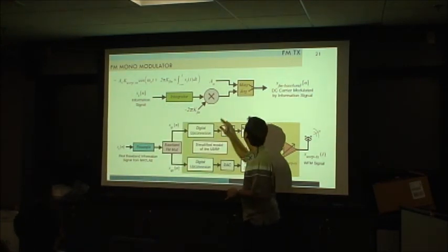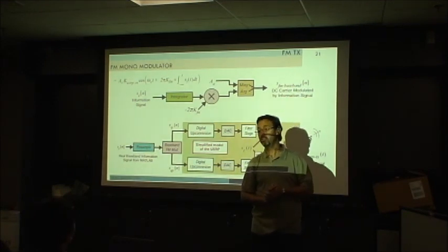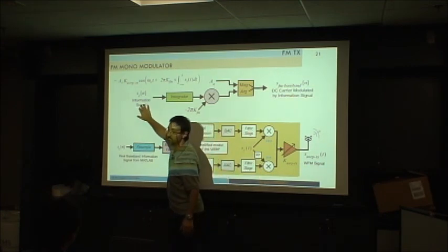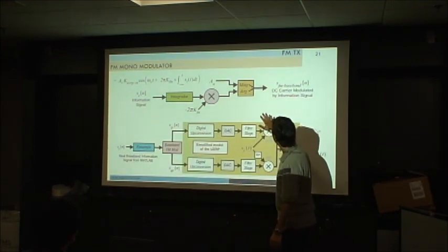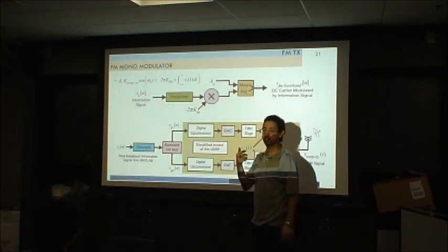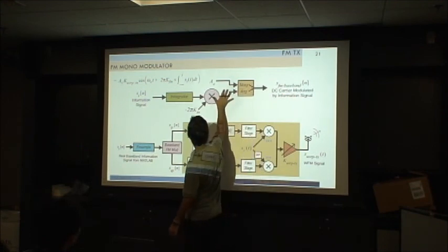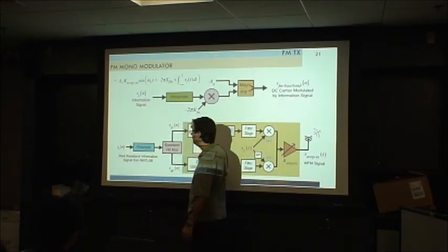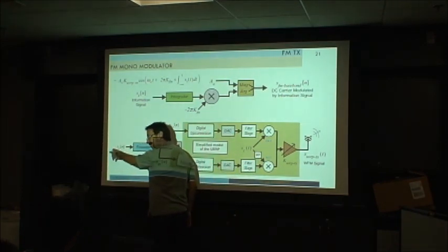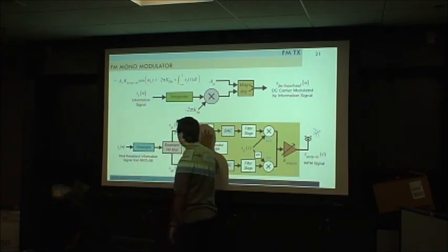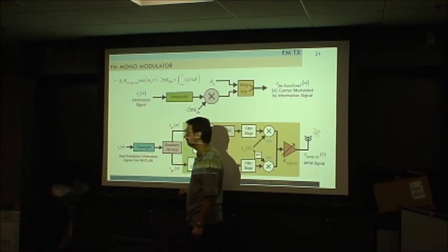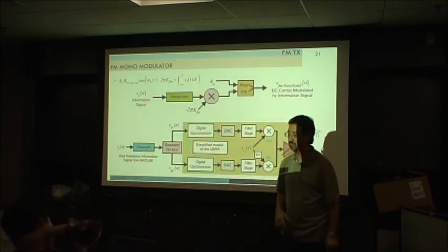So remember that here we are adding the base frequency plus the frequency that is moving, and that frequency that is moving is related with this information signal, of course. This will be how we implement our modulator. If you follow, this is exactly the same as this box. Here we will have some audio stuff. We will resample to reach the DAC sample rate, whatever. And this will be our FM modulator. And then the SDR.